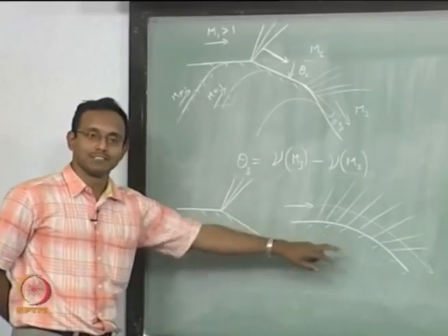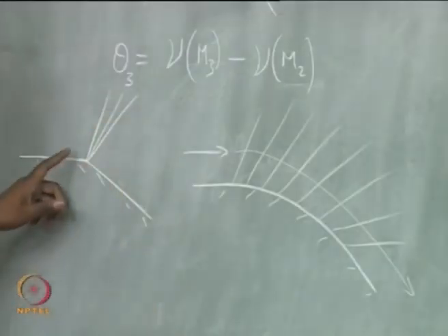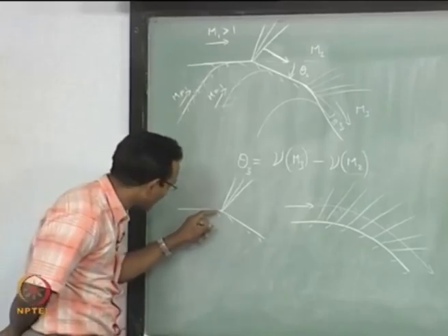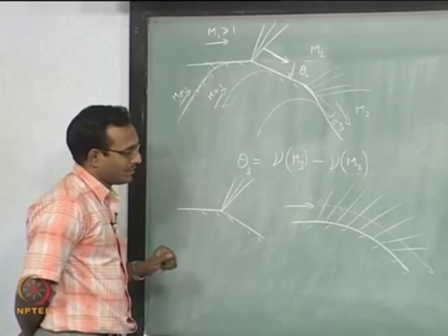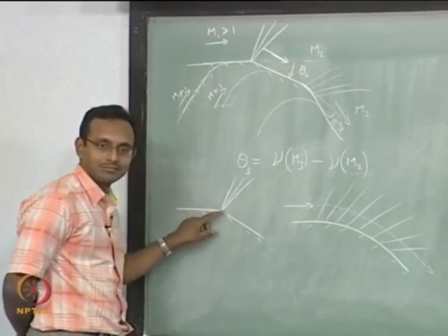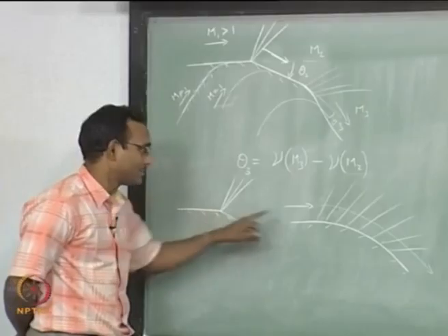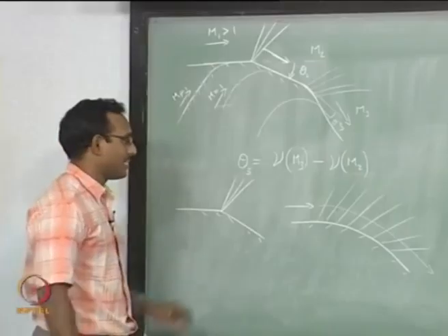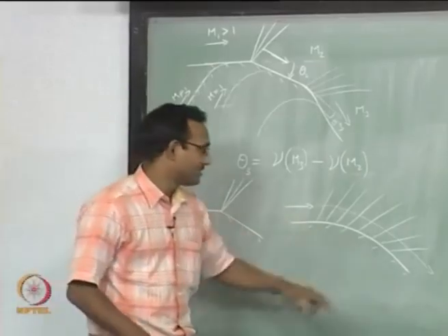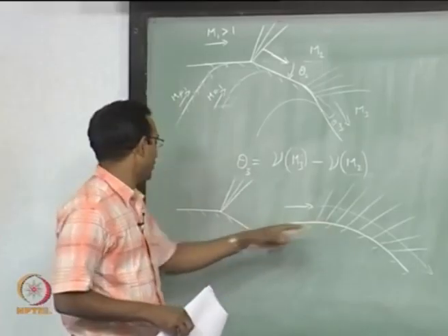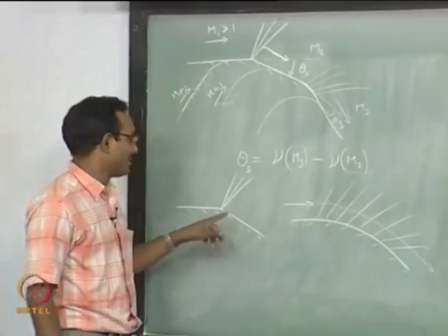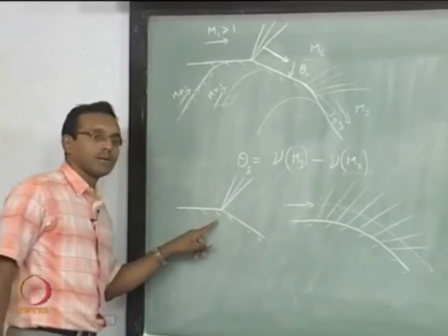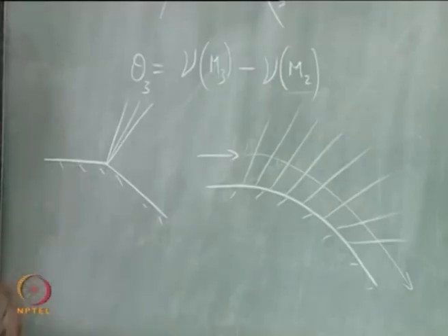Now the only other thing I have to think about: how will I relate this and this? If I really zoom into this region and just see what is happening at that corner alone, there will be a point where it will become a radius, because of mechanical machining, whatever. It will always be this form. If I zoom out of this problem, this radius will become a very small change and eventually it will look like this. This is what they call a smooth corner, the change is slow, and this is a sharp corner or a sudden corner, a sudden change in angle.